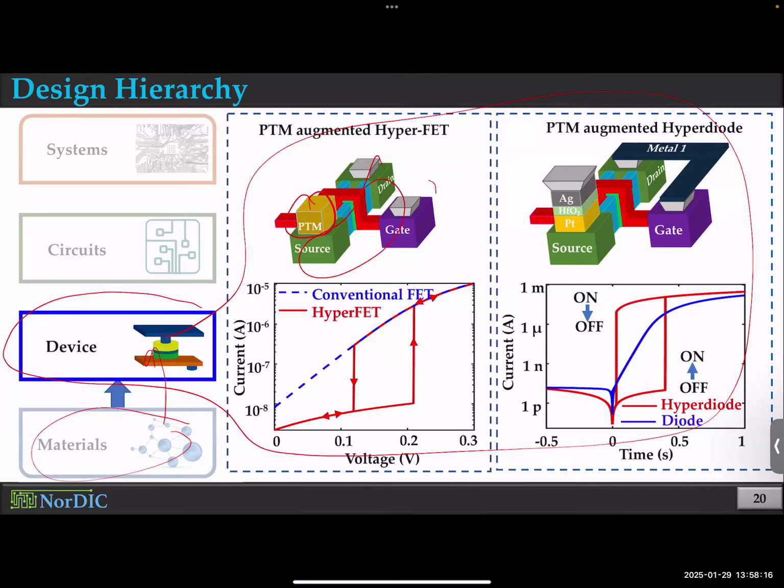That doesn't mean the device level research doesn't have impact. Basically, that's the most critical thing. You know why? I told you the answer in the last class. Memory is uniform. Whatever you do to the one device will be done to all the other devices. So you optimize and design the device to the fullest extent that you can. Once you make sure this is the best possible spintronic device that I can make in this technology, the best possible ferroelectric that I can possibly handle, there you go, you have one cell. Then you just repeat that device over to arrays and you have your memory array. And then you do the other architecture stuff. So definitely device level research requires a lot of attention.